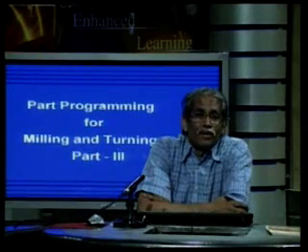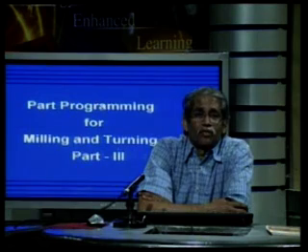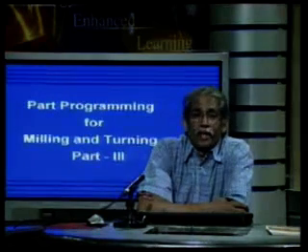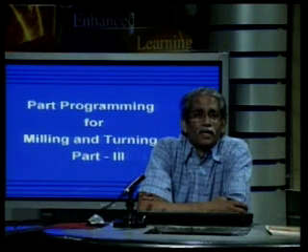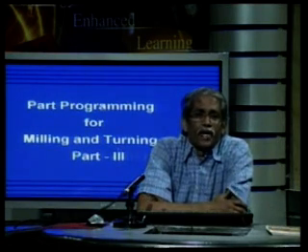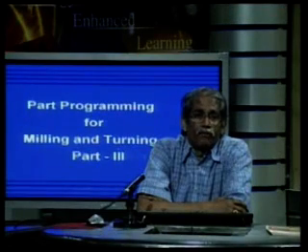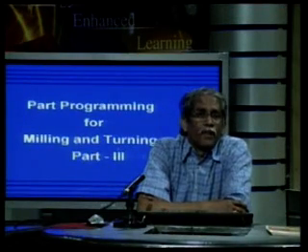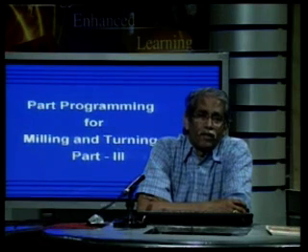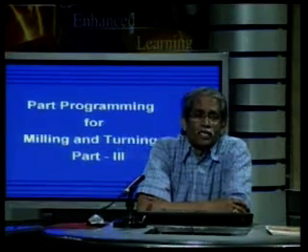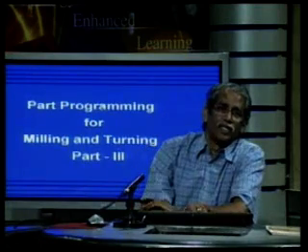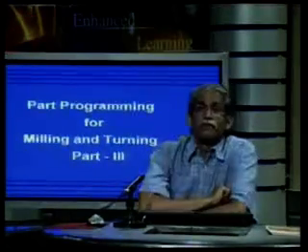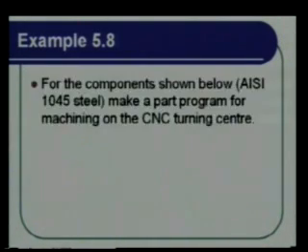Now again you will have to identify all the points through which the tool will be going. So you need a large amount of coordinate calculation in terms of cut planning. So again I suggest that whenever you are doing the cut planning, make use of any CAD program that you are familiar with or have access to, so that calculation of the coordinates becomes much easier. Now I am showing you an example here for the purpose of calculation.